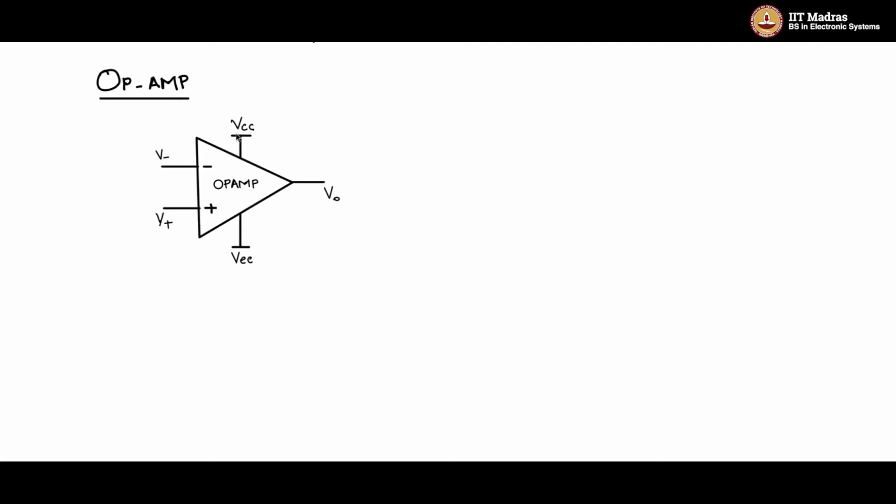After we have created a model, we have to create a symbol in KiCad, and then we link the symbol and the model. Then we have in our library a generic op-amp customized component which can be used for any circuit, schematic and simulation. So let us do that.